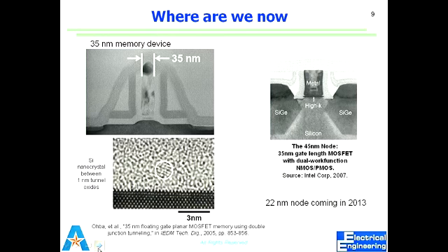Right? So this is to show that when you say uniformity of oxide thickness, this is a few atoms thick oxide, and it has to be precisely that. It has to be uniformly that thickness all over the device. This is just one transistor, and we have billions of transistors in one die, right? One chip. And then on a wafer, we have again thousands of those dies.